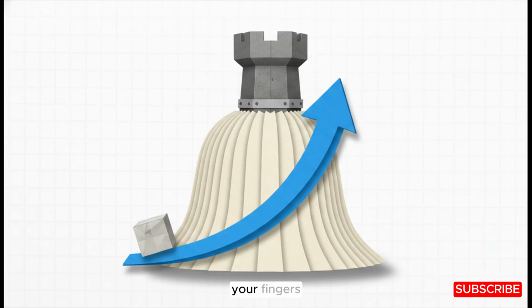Instead of crossing your fingers and hoping for the best, the design mix uses this statistical formula as a risk management tool. Out in the field, concrete strength varies naturally on a bell curve. We don't just design for the bare minimum characteristic strength. We design for a target mean strength that is intentionally pushed higher by exactly 1.65 times the standard deviation of our materials. We are mathematically programming our quality control right into the formula to ensure a 95% success rate.